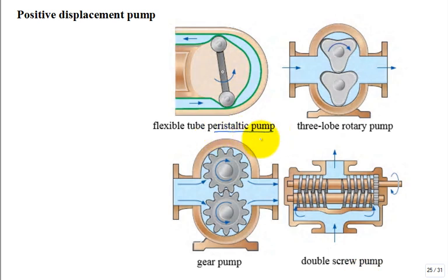Peristaltic pumps, so they'll have a flexible tube, and they'll have a device that's rotating, squeezing and pushing a trapped amount, and it can deliver, guarantee, that flow rate. So the nurse can come in there and look at the doctor's orders and then verify or move that knob to give you the right flow rate for whatever IV you're getting. This one's very common in chemistry labs, physics labs, just when you have to deliver a specified amount over a long time period, very controlled.